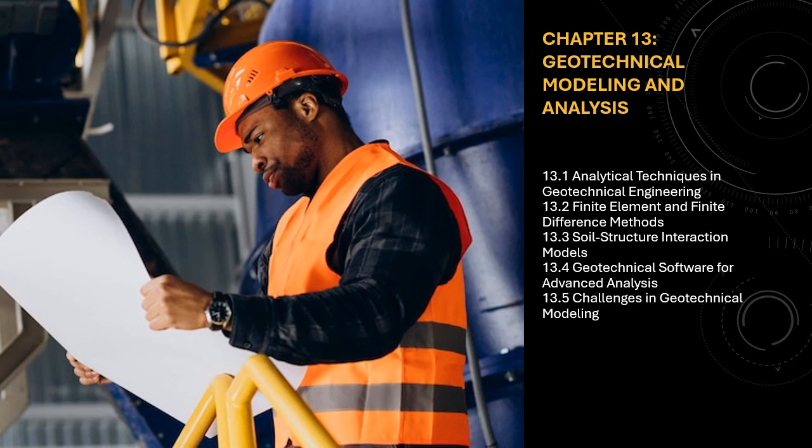13.1.1 Closed-form analytical solutions. Closed-form solutions are mathematical expressions that allow engineers to directly calculate the desired values based on known parameters, such as soil properties, loads, and boundary conditions. These solutions are generally applicable in relatively simple geotechnical problems where the assumptions of linearity and idealized behavior hold.